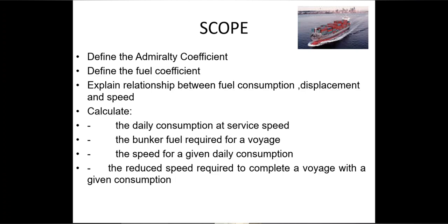This is a practical thing on board, that a certain amount of fuel at the bottom of those big tanks remains unpumpable. However small it may be, it is definitely a quantity which may be 20 tons, 10 tons. It varies from ship to ship, and also based on trim. Sometimes with a good trim it can be transferred. So these are the various possibilities where we need to know how much bunker should be there or how much speed we should move with so that we reach safely.